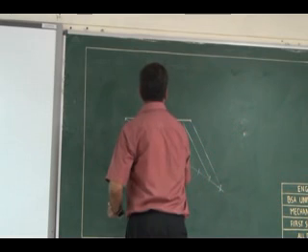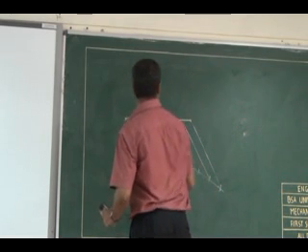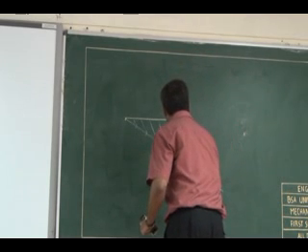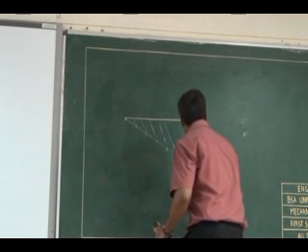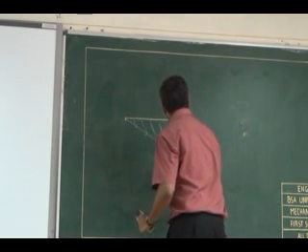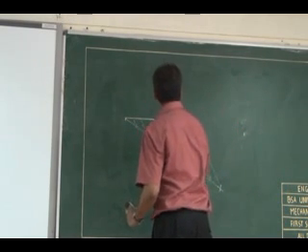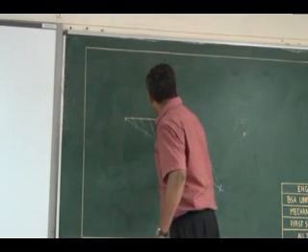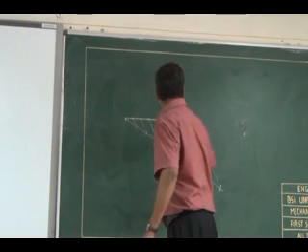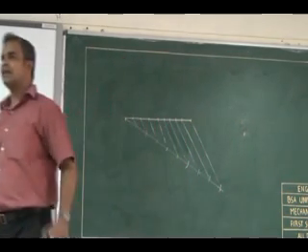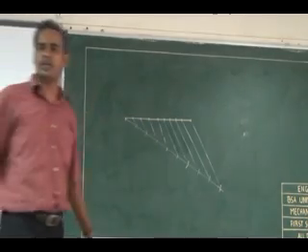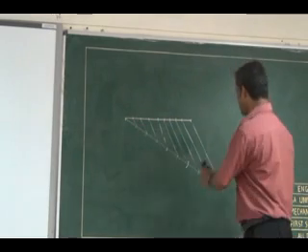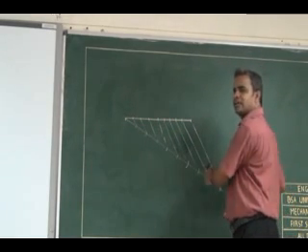Divide the original line like this. Now these locations are the divisions, 9 equal divisions I have in my original line. So what you can do, the extreme line you can join it, connect it with a 2H line.